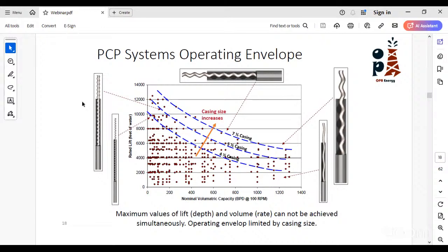If you require very high pressure from the system, of course, this system cannot give you the maximum flow rate. You cannot combine a very high flow rate with a very high differential pressure, because the system can work in either condition. You can get a very high flow rate, of course, but the total dynamic head that you get from the system will be low, because of this inversely proportional relationship.